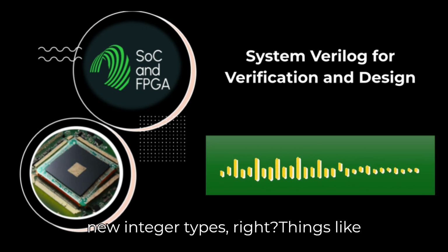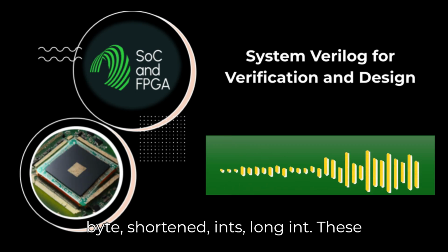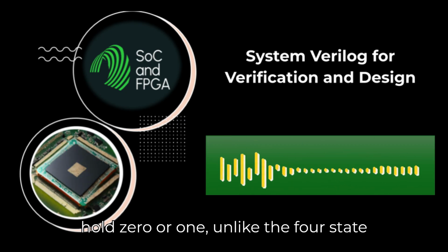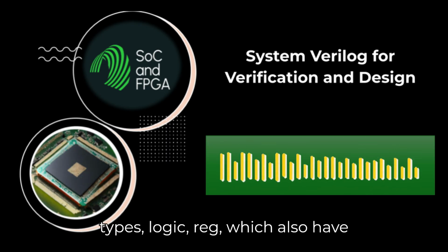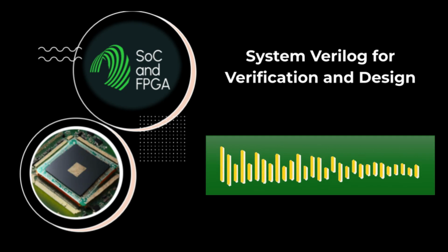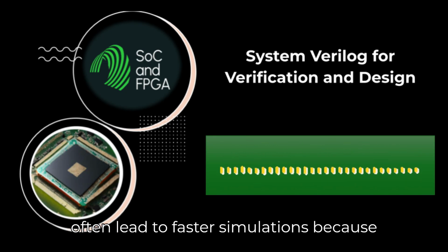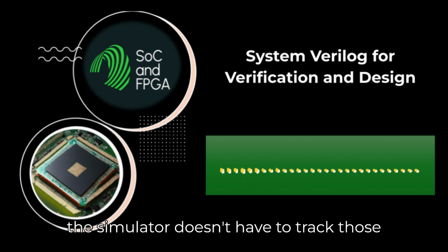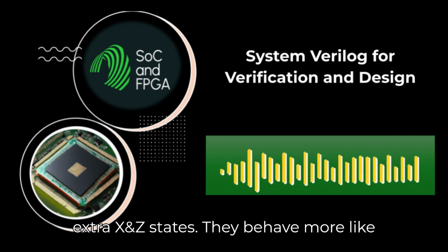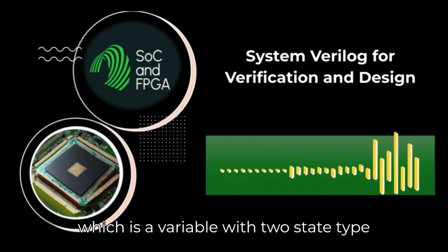You also mentioned new integer types. Right. Things like byte, shortint, int, longint. These are two-state types, meaning they only hold 0 or 1, unlike the four-state types, logic and reg, which also have X for unknown and Z for high impedance. Why is that useful? Two-state types can often lead to faster simulations because the simulator doesn't have to track those extra X and Z states. They behave more like software integers. You also get bit, which is a variable with two-state type.